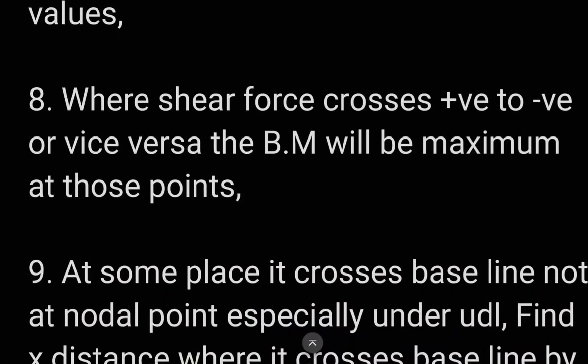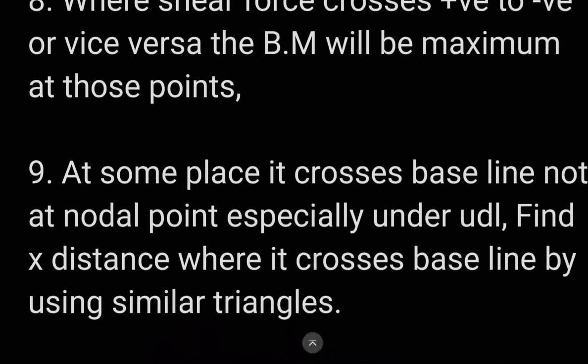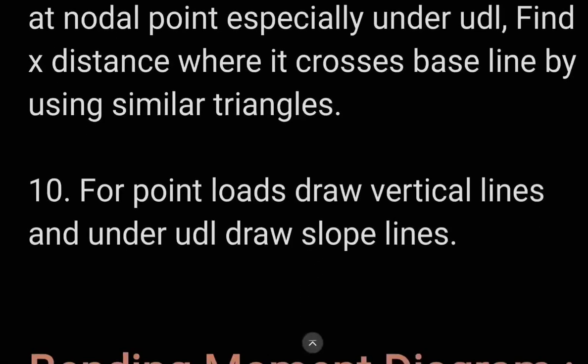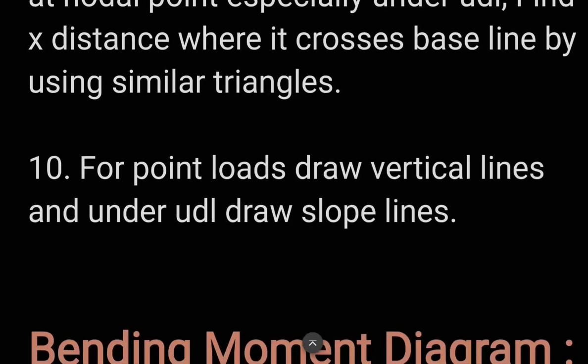Number 8. Where the shear force crosses from positive to negative, or vice versa, the bending moment will be maximum at those points. Number 9. At some places it crosses the baseline not at a nodal point, especially under UDL. Find the x distance where it crosses the baseline by using similar triangles. Number 10. For a point load, draw vertical lines. Under UDL, draw slope lines.